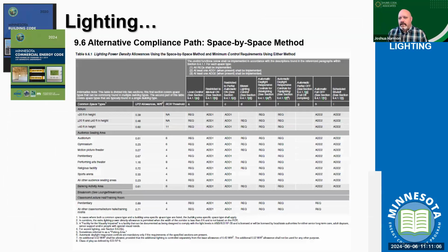And so what we'll be looking at is again, what are those different expectations for lighting conditions? And so we're going to treat things differently based on, are we looking at maybe facade lighting versus parking lot lighting? What types of timers, or when do we need to have vacancy sensors or occupancy or motion sensors? When are we evaluating safety versus just general lighting for a particular area? All of those considerations come into play when we start calculating some of these different designs.